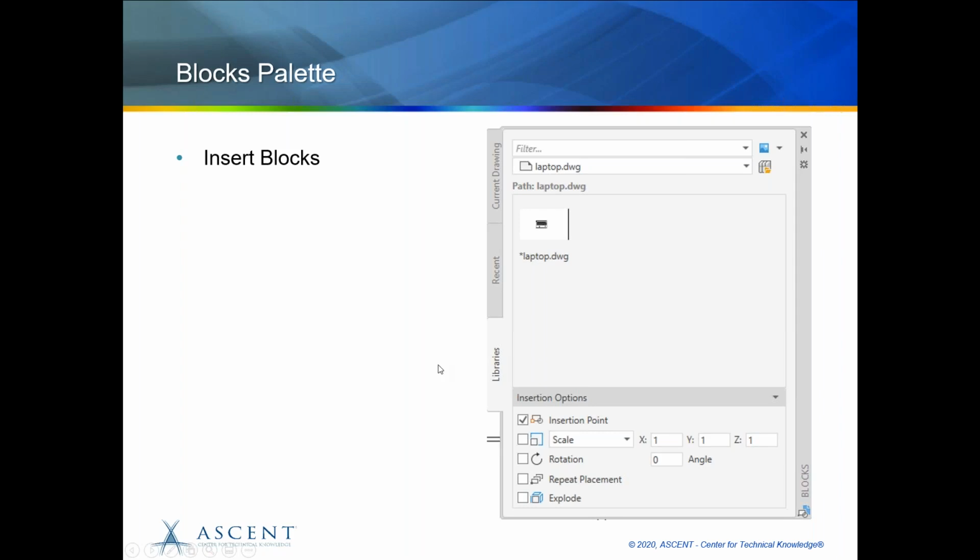And now in the libraries tab, it allows you to insert blocks from other AutoCAD drawings as blocks, which was normally done with the insert block command. But this year, what they have added is a navigation tool up here. When you select it, it opens an open block dialog box, and in that dialog box, you can select a folder. In that folder, if you have multiple drawings, all those drawings will be included in your current drawing as blocks.